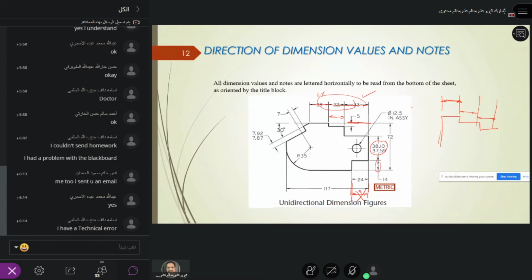This is very good. And see the leader. The leader is taken out and it's a diameter 12.5. So it indicates that this circle has a diameter of 12.5 and you take it with the leader. So either way you can draw it, and the radius is here. So radius from the center, either you can write it here like this, or you can take it out, 35. These both are okay.